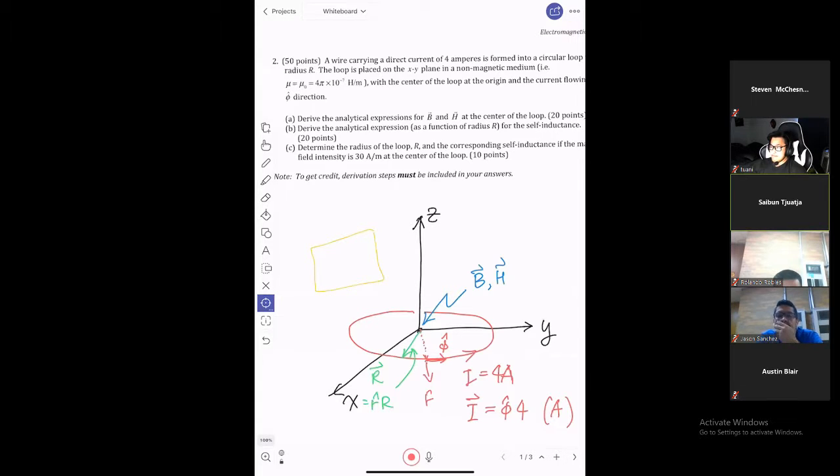Self-inductance, I can have the self-inductance of this guy by itself. Suppose I have a current flowing, let me use a different color here, like this. Let's call this current I2. This current I2 produces a magnetic field, and the magnetic flux captured by this area, divided by this current I2, is called the self-inductance for this particular circuit, this particular setup. The self-inductance for this guy is this current's produced magnetic flux captured by this area here. The ratio of that is the self-inductance of this part.